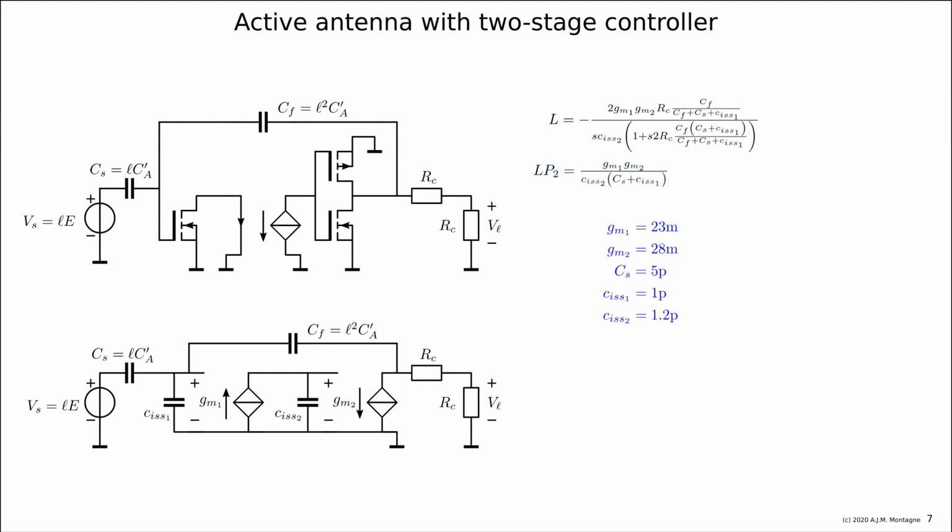So I did something in between the last presentation and this one. That is, I optimized the noise and the drive capability a little bit, and this gave me another input capacitance. Maybe you remember that the input capacitance should be equal to the antenna capacitance to have the lowest corner frequency of the 1/f noise. And in my previous simulation with SLICAP, you can see it on the video, it turns out that this corner frequency was about 30 kilohertz. But 100 kilohertz would be good enough.